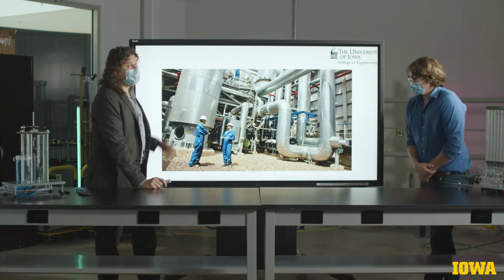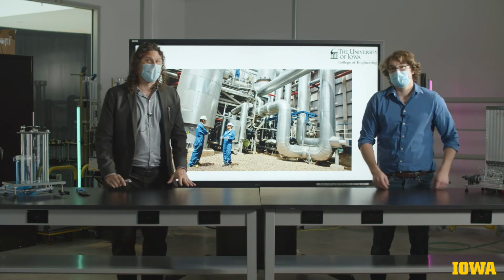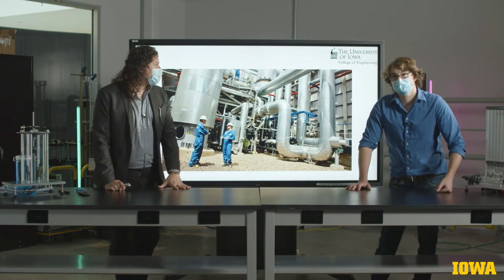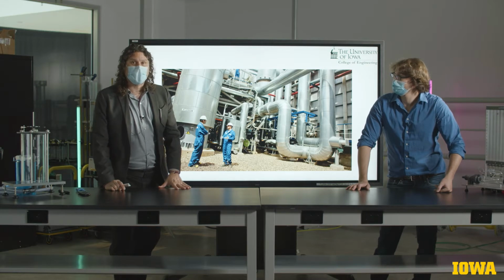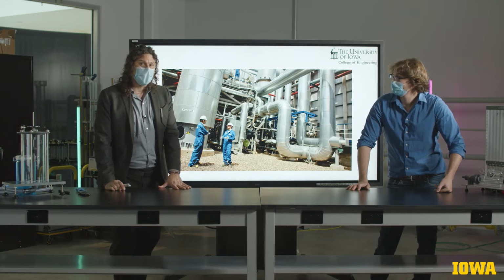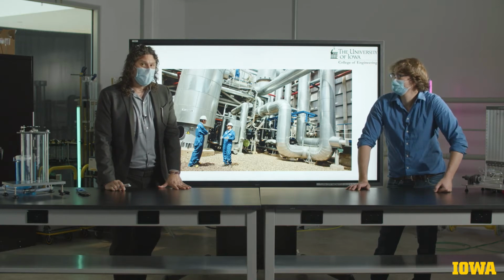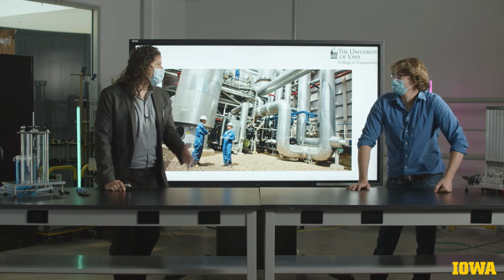The other big advantage of the experiment that we will be conducting is that it lends itself very well to dimensional analysis. So everything that we learn on circulating air through these pipes will be applicable to the movement of other fluids.